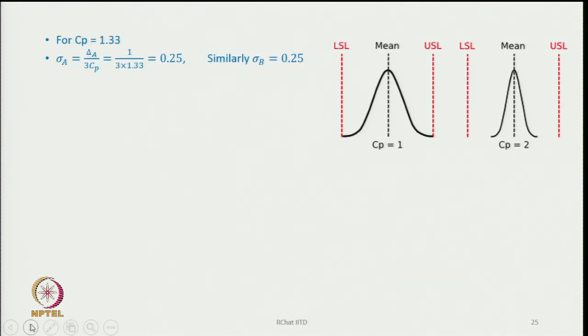So, we have found out the target value of the packet, that is C. Now, we still need to know what should be the tolerance. That calculation is still left. So, Cp has been stated to be 1.33 for the process which is folding the fabrics and making them 20 centimeter and 10 centimeter for fabric A and B. In that process also the nominal value is 20 or 10, but the process capability Cp value is 1.33. That means, sometimes we get 20 plus something, 20 minus something.